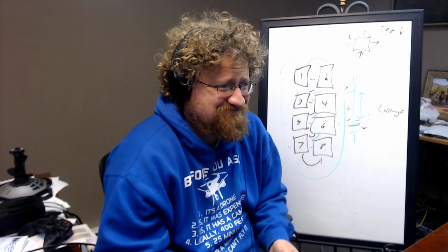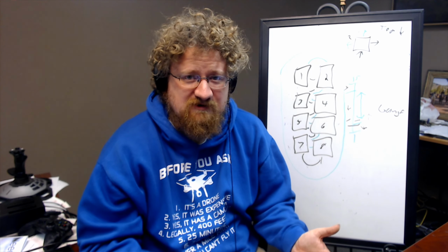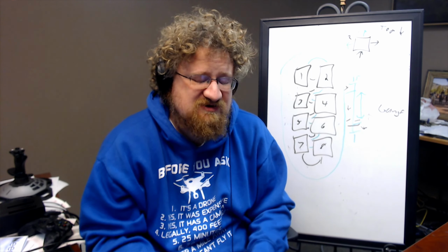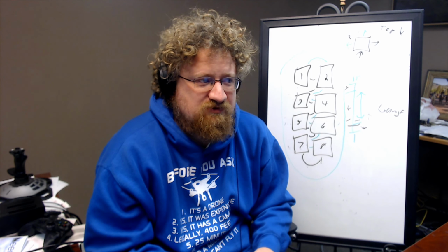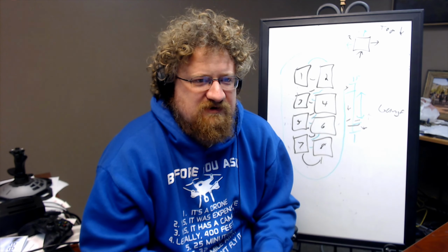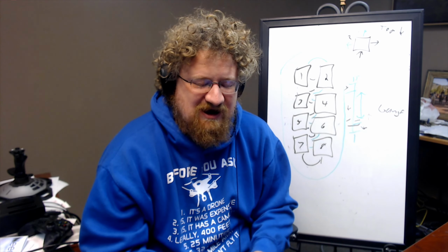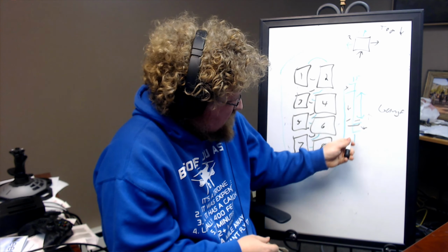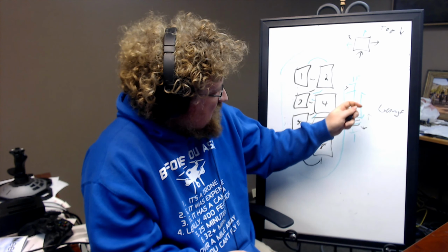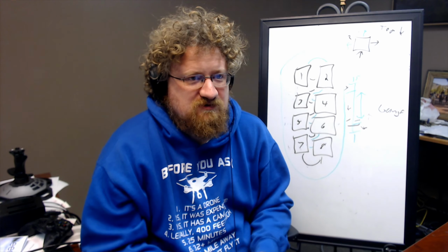Now, I can send back readings that will tell the computer how charged the battery pack is overall based off of the 8 batteries. And it can be programmed digitally via memory systems in a way, via some interesting zero binary programming. It can be set up to start charging the substation after 4 of the batteries are down here, and then stop when they're all up here. Or it can be set up for when 6 of the batteries are empty, or it can be set up to start when the entire battery bank is empty.